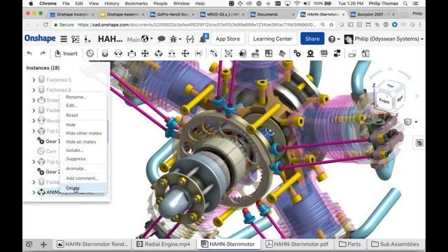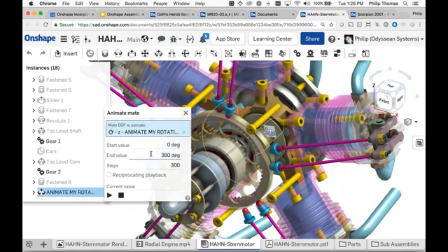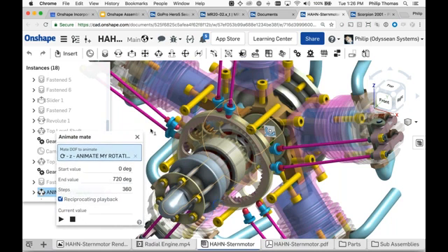ball bearings. So whenever I build an assembly, if you see it in block capitals, feel free to animate it. So I'm going to animate the rotational degree. I apologize, I'm not teaching you how to do animations, I'm just telling you how to make it work. From 0 to 720 degrees in 360 steps. This will go ahead and generate a full-on kinematic analysis.